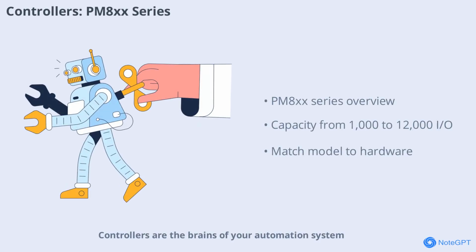Controllers are the brains of your automation system. The PM8XX series CPUs range from the compact PM856, suitable for small skids with around 1,000 I/O points, to the powerful PM891, designed for large plants and SIL2 safety applications with up to 12,000 I/O points. Selecting the right controller for your project is crucial, as it determines the system's capacity and reliability. Always verify the controller model in your project matches the hardware installed in the field to ensure seamless integration and operation.